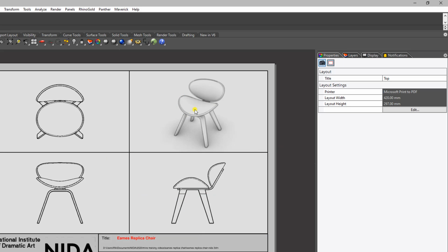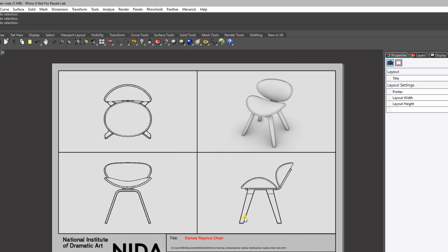And we can't set a scale for our perspective view because it is a perspective view, so you can zoom in and zoom out of that, but we can't set a scale for that. So again, once you've done that, what we might do is just add some information about what those different views are. Now, you know that that's a top, a front and a right, but someone that receives a drawing or someone that you send this to, it's nice to annotate that on the drawing itself.